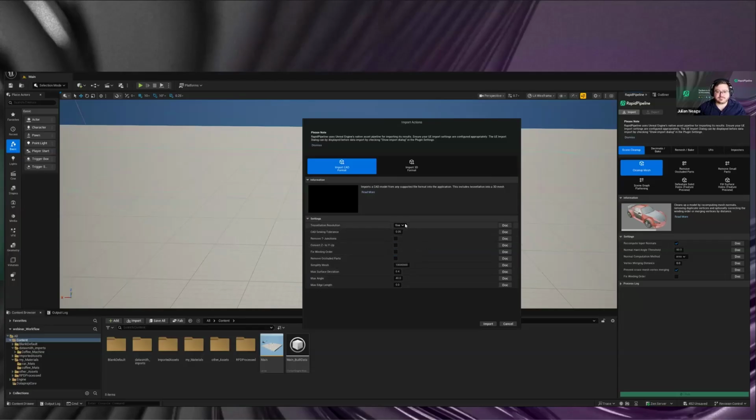So let me go just with the fine tessellation for now. We have the option to remove T-junctions, which is quite important. Sometimes in the tessellation process, we actually have very thin triangles, overlapping triangles. We have vertices, which are basically dead ends, not connected with a representative edge to form a good triangulated surface. So this is something which cleans that up.